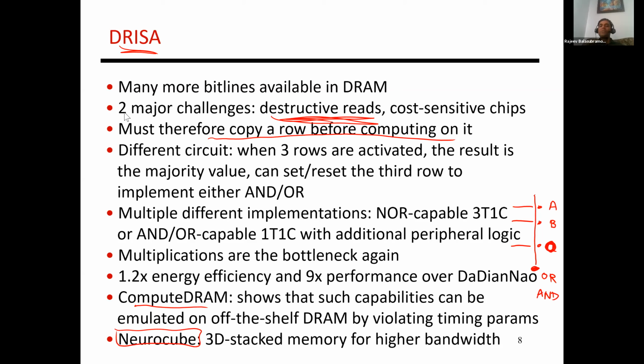Somebody had a question about, does the wire operate as an AND? Yes, that's essentially what is happening. When you have multiple DRAM cells connected to the same bit line, some of the cells are adding charge and some of them are essentially acting as a ground. People have empirically shown that depending on what the majority of cells are doing, you're going to get that majority result.